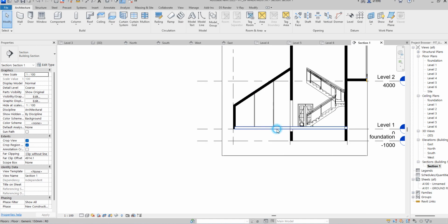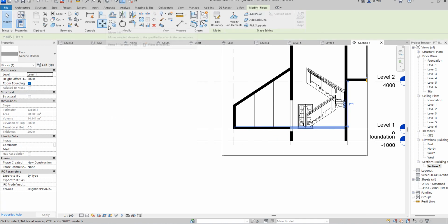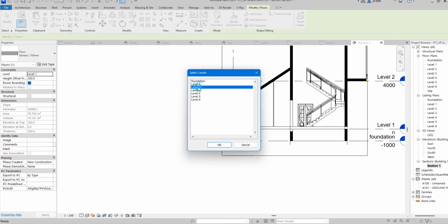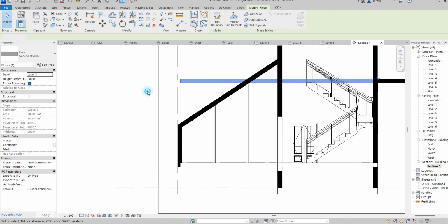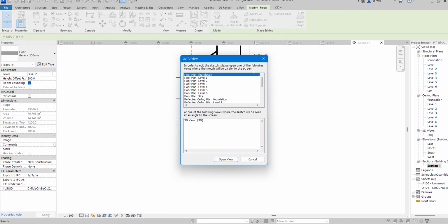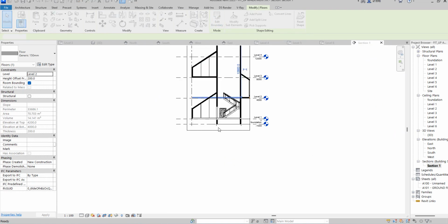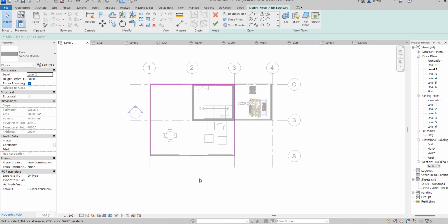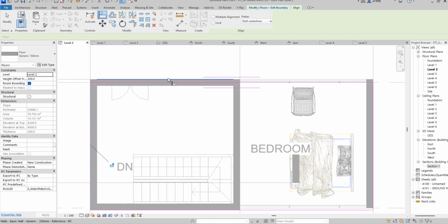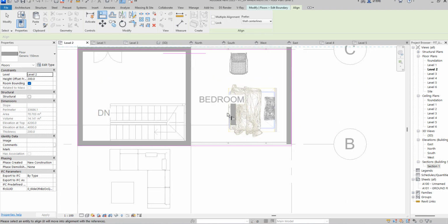So what am I going to do here? I'm going to bring this floor to use. So just say copy and then paste, align to level 2. Good. So I have it there. So I need just to do the editing. So I do the boundary, go to level 2, open it up, then align to where it's supposed to be aligned to, just a direct trace. So click here, then finish it here. This one is here too. So that is it. You have been able to connect them together.